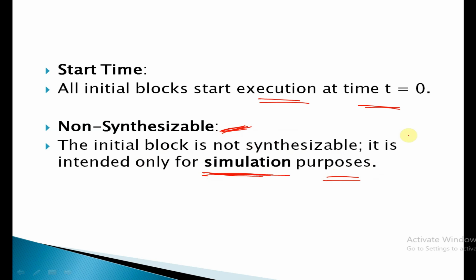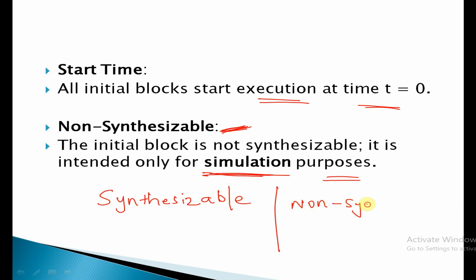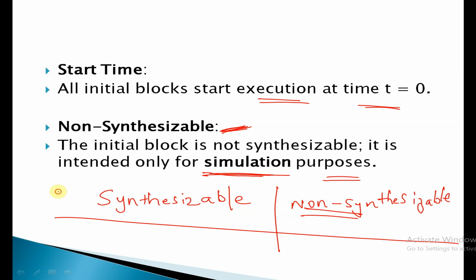So what is meant by synthesizability? This I have told you: in Verilog there are two types of coding styles or constructs, you can say. One is synthesizable and another is non-synthesizable. So you should be very careful when you are using these non-synthesizable constructs, because these are not going to get synthesized, or you cannot use them with your hardware. These are only for testing purposes. So you can note it down in your notes or somewhere, whenever we encounter these particular non-synthesizable things.